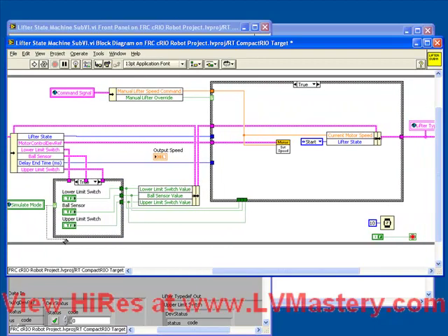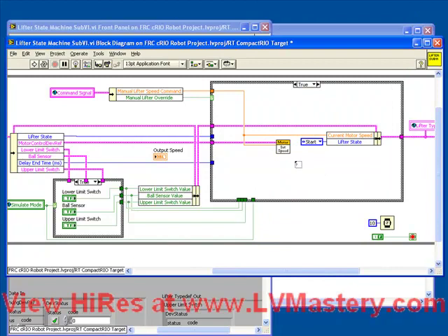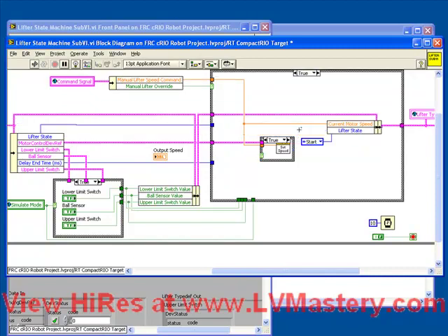So let's take a copy of this simulate mode right to our case structure. All we need to do now is case out all of our motor set speeds. Put case structures around every one we find. And usually the act of doing this means you have to make a bit more room in your block diagram in order to get everything to fit properly, which often means having to clean up the positioning of wires a little bit. But again, if simulate is